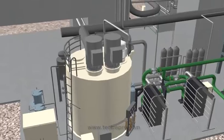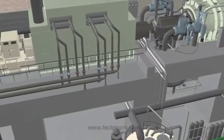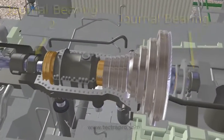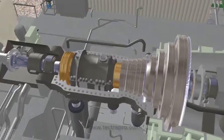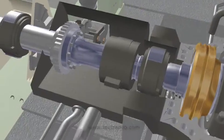Turbine generator lube oil is pumped from the tank, through one of the lube oil coolers and the oil filter, then on to the turbine and generator bearings. The steam turbine generator contains 5 journal or support bearings. Journal bearings are numbered 1 through 5 from the condenser end of the steam turbine to the exciter end of the generator. A thrust bearing is located next to journal bearing 2.